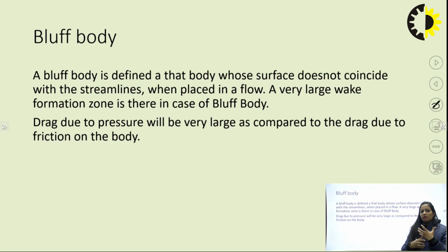Whatever the wake zone, how large the wake zone is shows how the bluff body is acting. The wake zone means the separation of the boundary layer is there. The drag force due to pressure will be very large as compared to the drag due to friction on the body. So this is how we can distinguish a streamlined body and a bluff body.